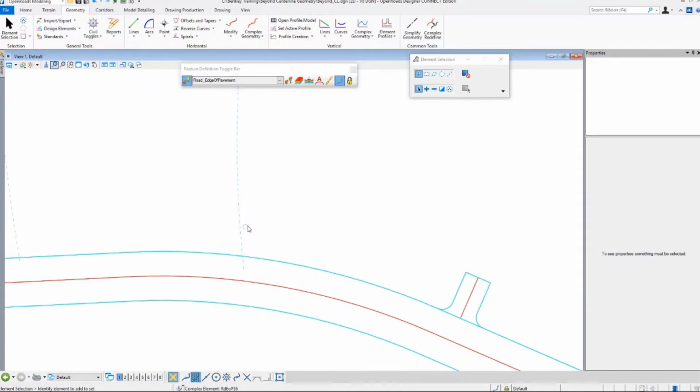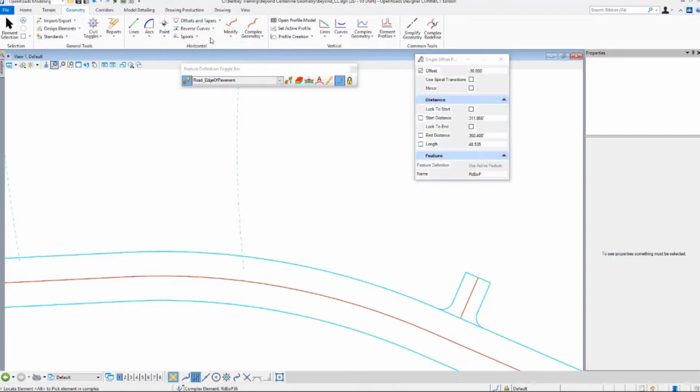So our goal on this driveway is to tie into this existing line. Now very often you have to tie in at the right-of-way line with a standard perpendicular to the road, different from this one. So we're going to start off with a partial offset. I don't have a right-of-way line in, so we'll just assume it's 30 feet off the edge of pavement there, and I'll say partial offset.